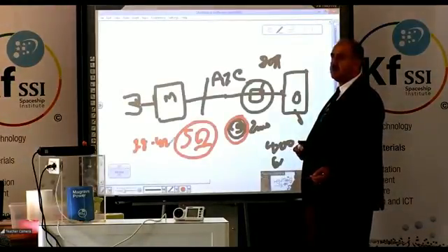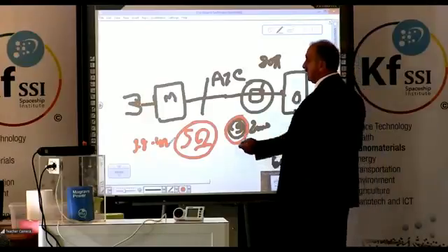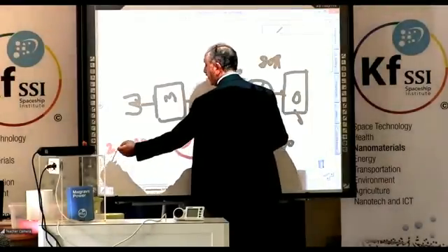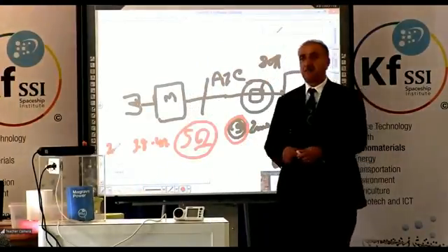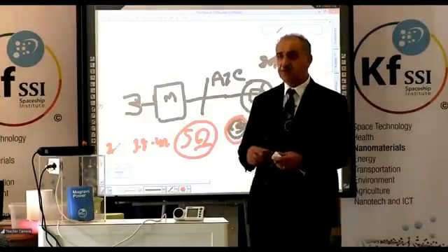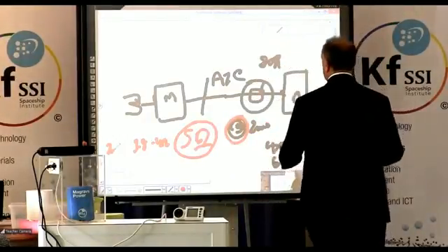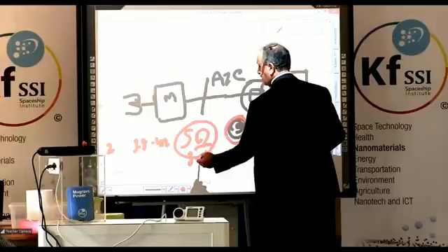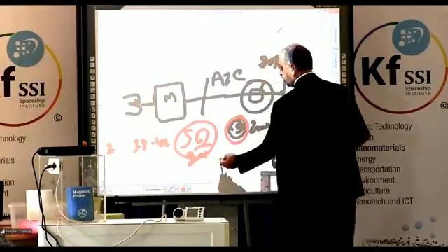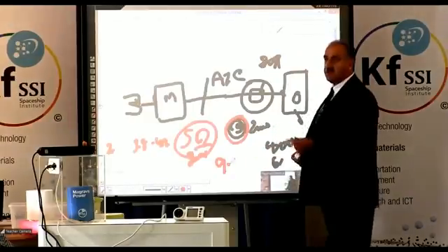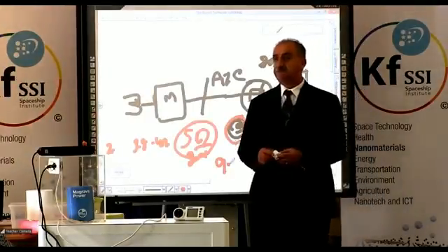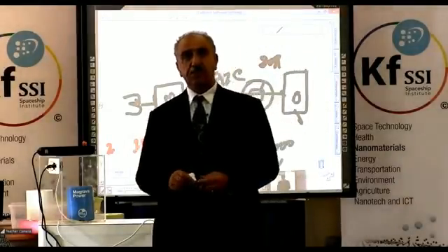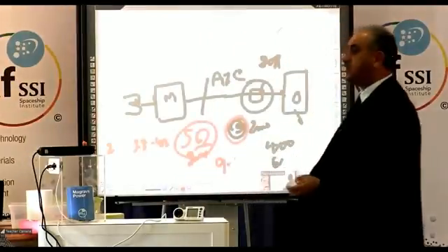This is how the system will go. If you put a second adapter to it, then you go around, let's say, 3 kilowatt of what is seen by the system. But if you look at it on this side, your 5.2 goes up by another 2.8 kilowatt, which means more or less you're sitting around a 9-10 kilowatt load. So a small adaptation, now we've seen it, is possible to do, and you just change the system.